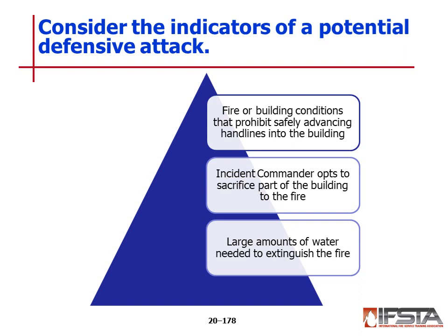When trying to stop the spread of fire through a single building, care should be taken not to push fire into uninvolved areas. The power of the elevated streams can cause furniture and other burning items to move to unburned areas, as well as create avenues of convection of heat. Movement of burning building contents can cause a change in the direction of fire spread and even reverse the rise of products of combustion in thermal columns. If possible, position the apparatus on the unburned side of the building. This allows the master stream to push fire and convection waves away from the unburned portion of the building.